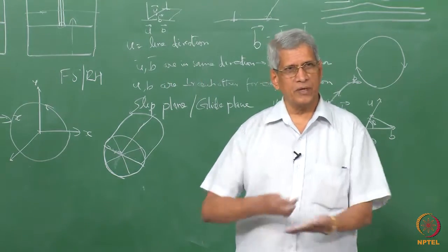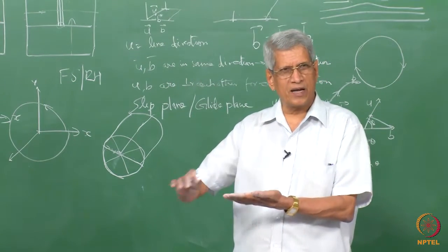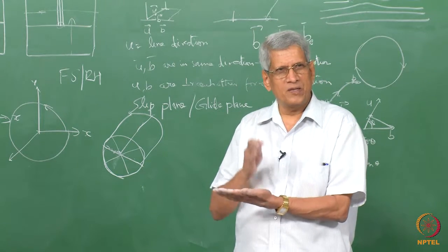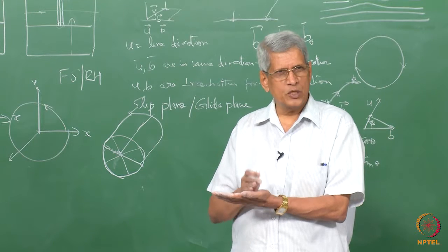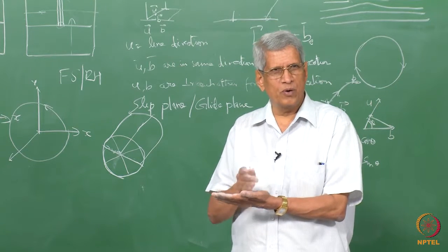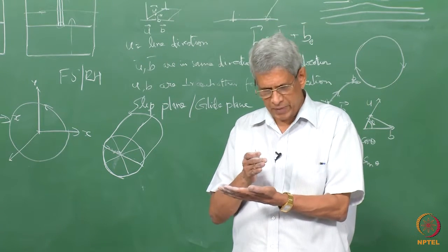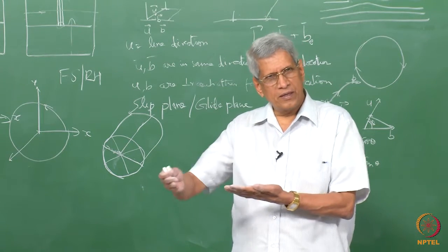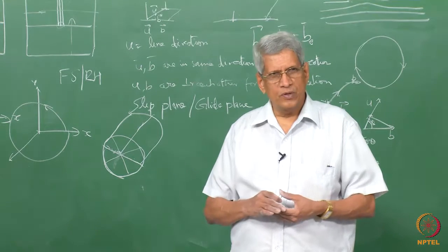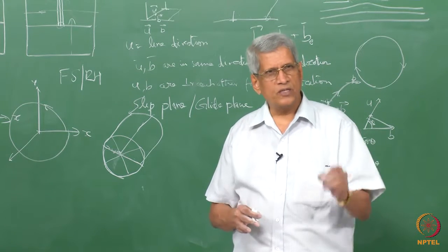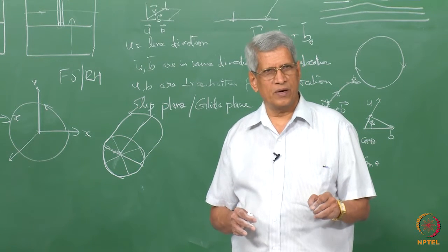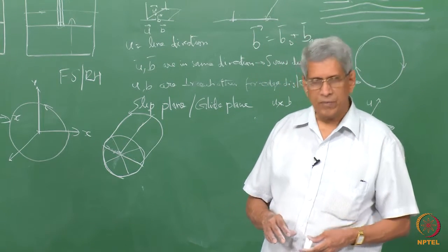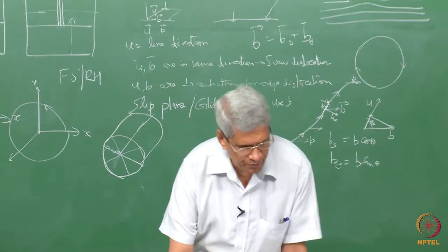Exactly like that, it happens with one layer of atoms, like a carpet sitting on another layer of atoms. By means of having a dislocation, just moving that step one at a time, breaking of bonds and joining of bonds, we can make the whole layer move. This is how a dislocation moves. That is why the energy required is extremely small when a dislocation is present.